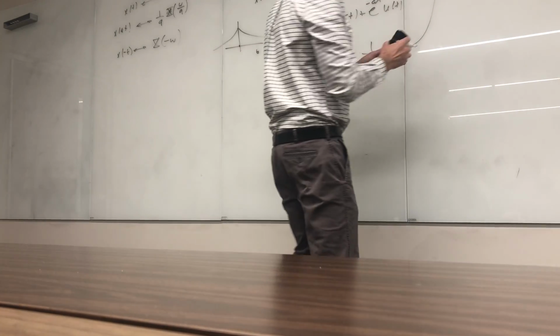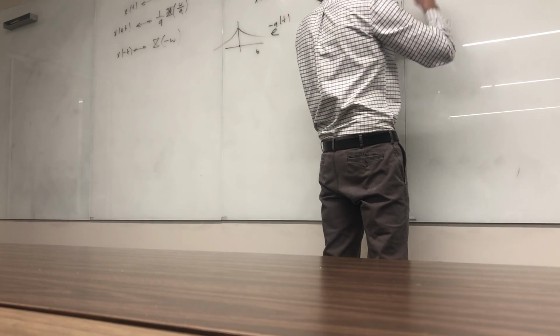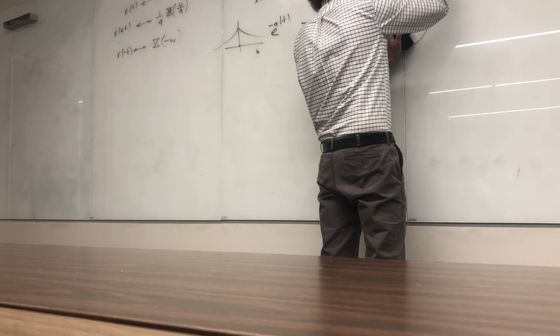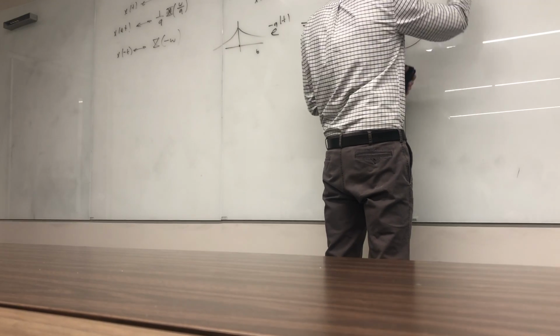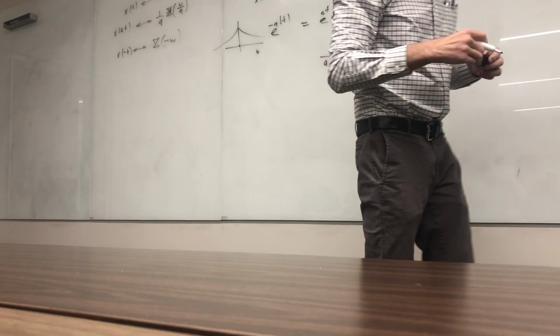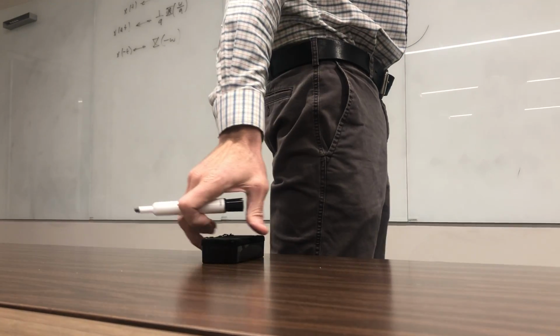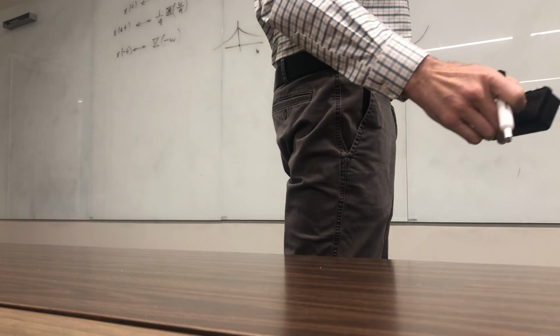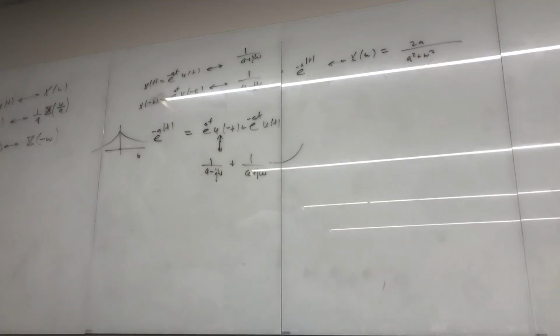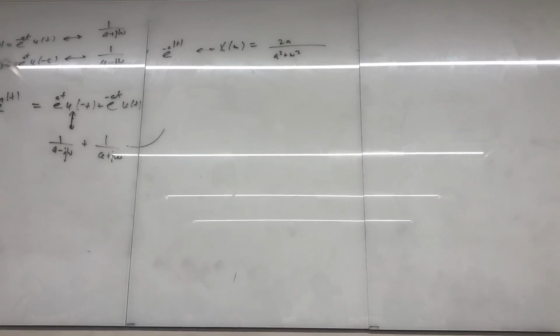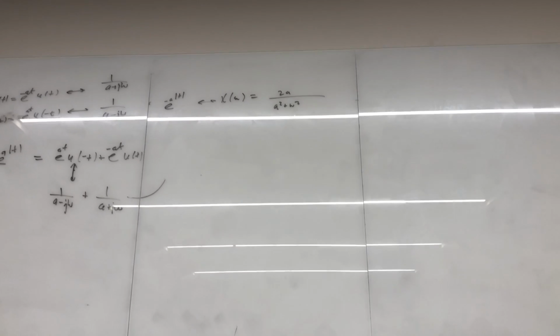That's the transform of e to the minus a magnitude of t. That's a transform pair. Now I gave you a problem where I wanted the, well, I'll get to that in a second, but you all see what I've done there? I need to put duality up there before I do that. The next thing. This is one way where you could use this transform property to really get the transforms quickly.